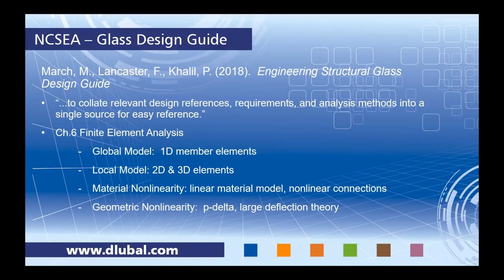With the global model within this design guide, they state that the glass elements can be simplified into 1D member elements. Now, this might be most beneficial just to gather internal forces, the load path, things like reactions, and to run a simple linear static analysis. Now, by all means, this is possible within RFEM as well.